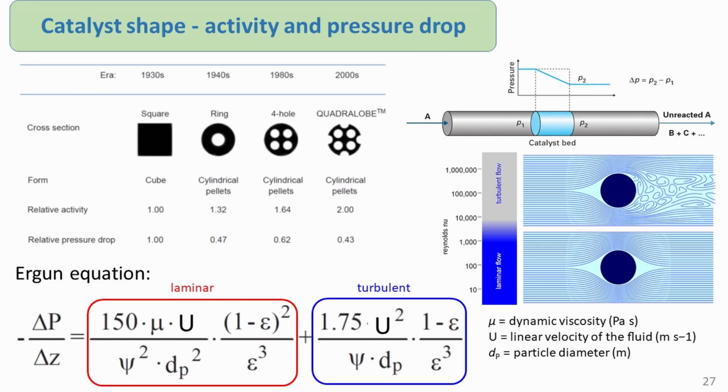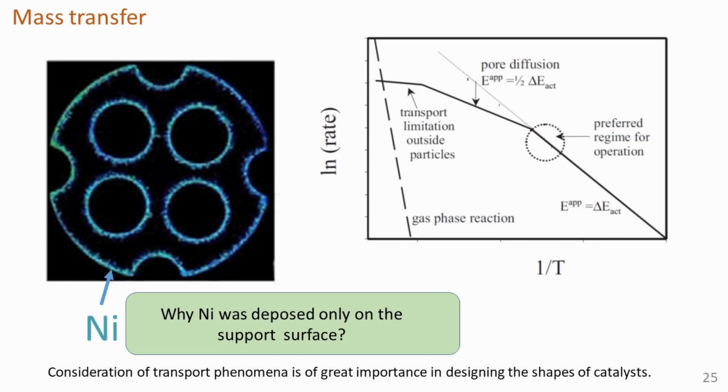The shape of a catalyst pellet should be optimized to achieve maximum activity with minimum increase in pressure drop. The pressure drop depends strongly on the void fraction of the packed bed and decreases with increased particle size. Similarly, the effective catalyst activity per volume is proportional to the surface to volume ratio of the catalyst pellets, due to the low catalyst effectiveness factor, typically below 0.1 for a tubular reformer.